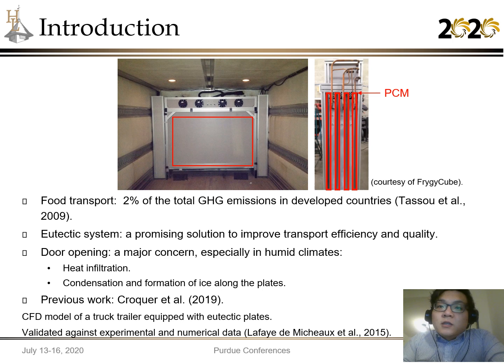However, for such a system, a major concern is the door opening period, especially in humid climates. The majority of heat infiltration for such systems occurs during the door opening period, and during this period, condensation and formation of ice and frost along the plates can occur, which interferes with the heat transfer between the plates and the surrounding air.